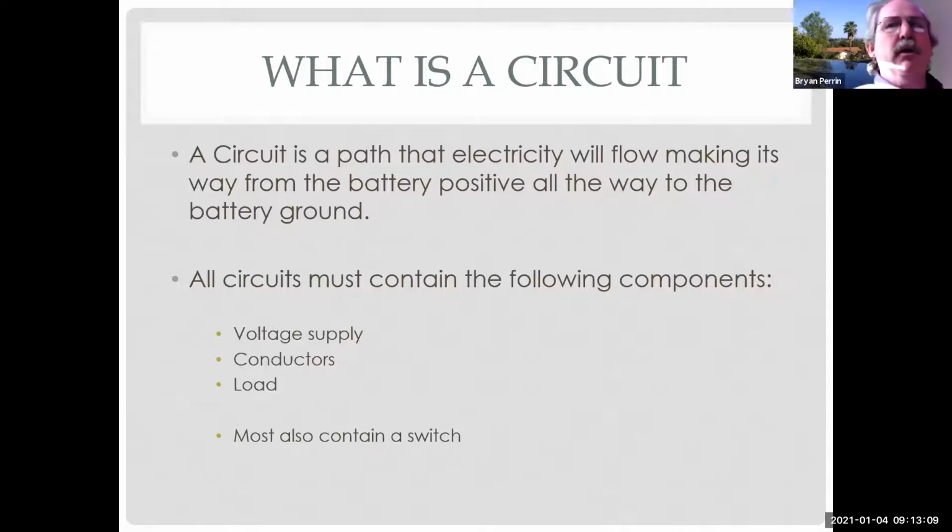But what if I have 120 volts through that same 3 ohms? Now that'd be 40 amps. The size of the resistance hasn't changed, but the size of the force pushing against the resistance has. So I'm going to flow more amps through that same amount of resistance.